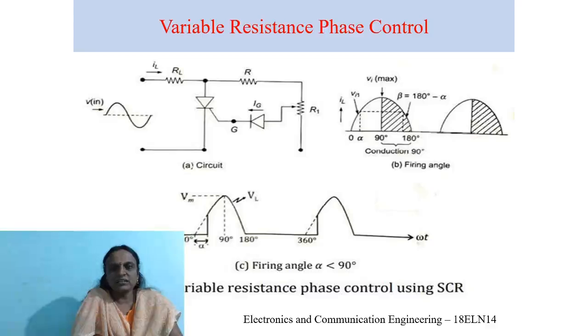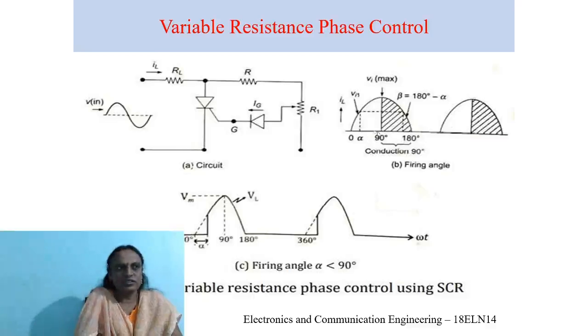On triggering the SCR, that is, turning the SCR on, only forward current is allowed. There is no reverse current because the current is blocked in the reverse direction. It is like a diode, which allows the flow of current only in one direction. But the SCR should be on for every positive half cycle of the input. Whenever it is triggered for every positive half cycle, it produces a constant DC current through the load and DC voltage across the load.